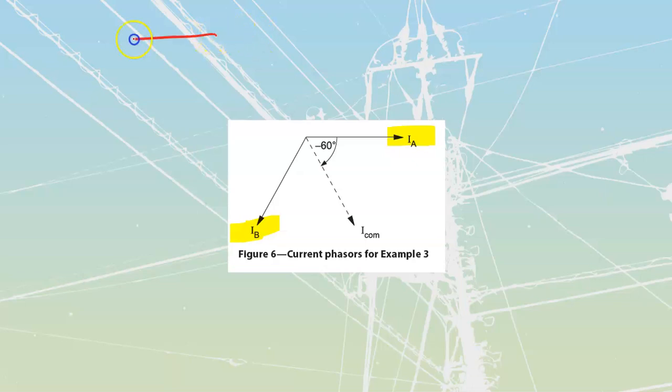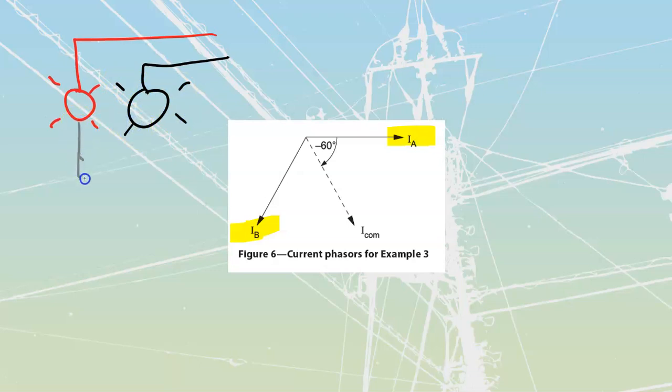We've got our A, we have got our B, and then we have got tying these 2 and carrying it back to our system. We are going to have our common over here. If we are 2.5 kilowatts and if we have got a 120/208 volt system, we know that if we're tying between a line and a neutral, therefore we must be seeing the phase value of voltage, not the line, but the phase.